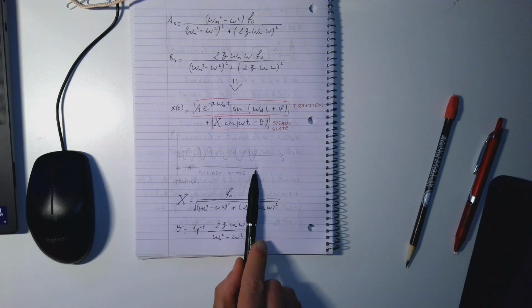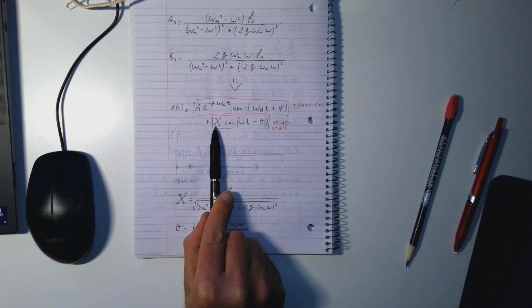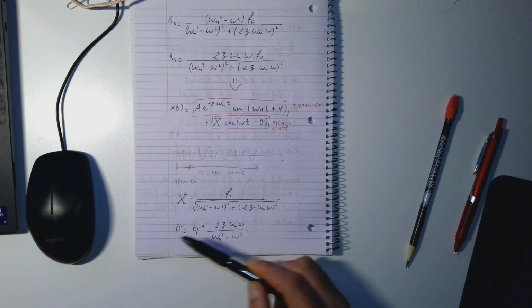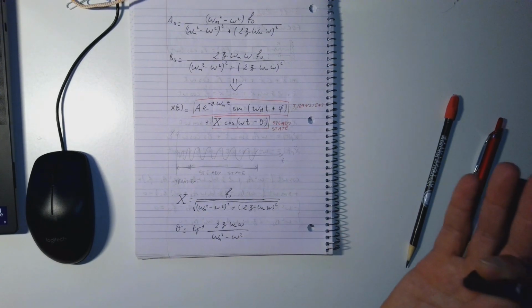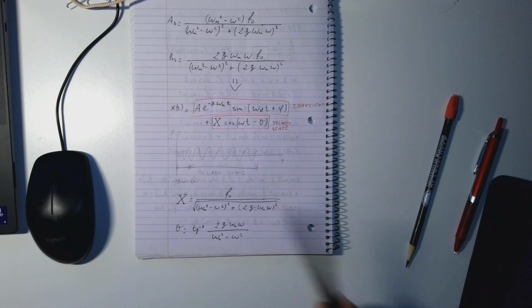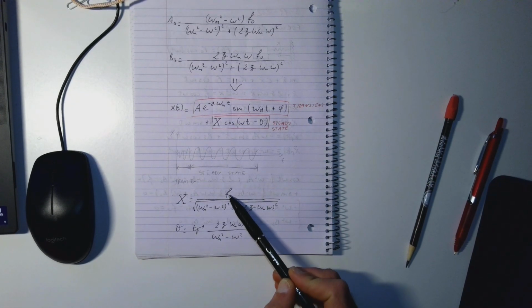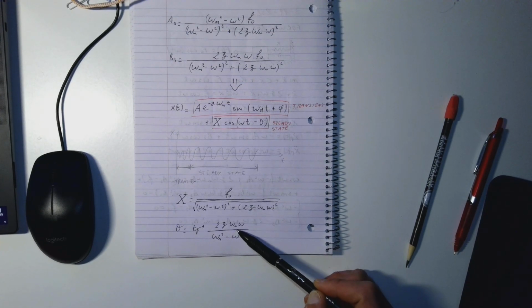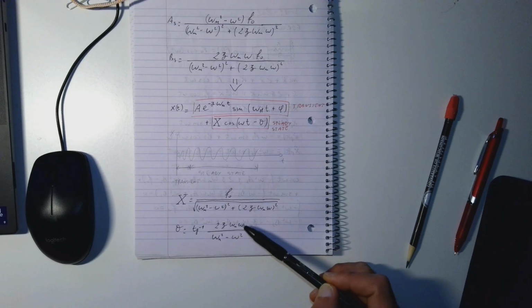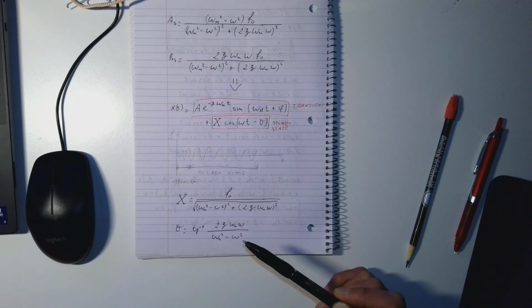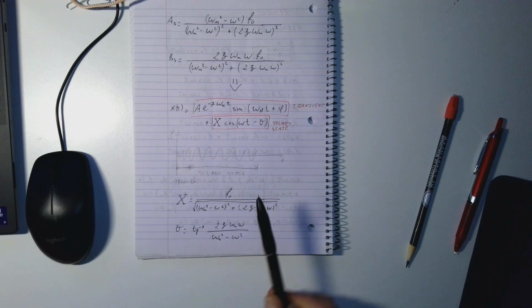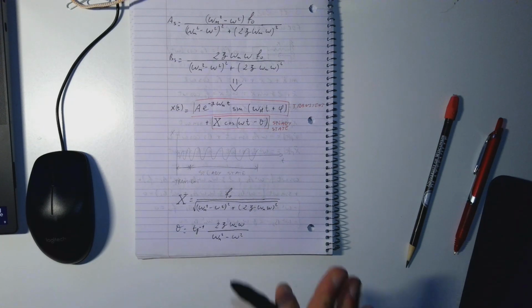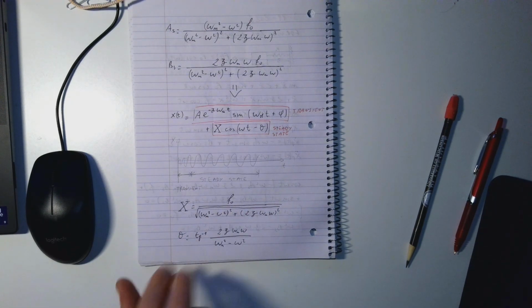And for the steady-state response, we still have these two constants, big X and theta, and we can find both of them as a function of the parameters of the system and of the external force. Because here we have lowercase f0, we have omega n, we have omega, we have zeta. Same thing here, we have zeta, omega n, and omega. So again, all the parameters of the system and the external force contribute to the amplitude and the phase of this steady-state response. Make sense? Any question?